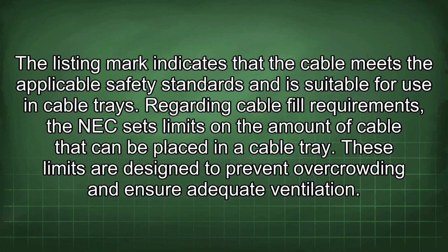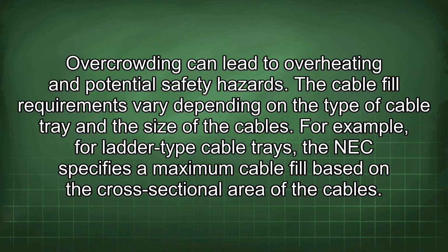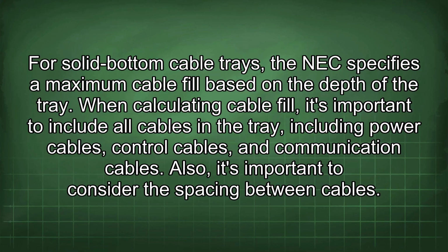Regarding cable fill requirements, the NEC sets limits on the amount of cable that can be placed in a cable tray. These limits are designed to prevent overcrowding and ensure adequate ventilation. Overcrowding can lead to overheating and potential safety hazards. The cable fill requirements vary depending on the type of cable tray and the size of the cables. For example, for ladder-type cable trays, the NEC specifies a maximum cable fill based on the cross-sectional area of the cables. For solid-bottom cable trays, the NEC specifies a maximum cable fill based on the depth of the tray.